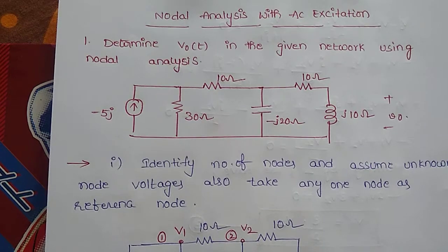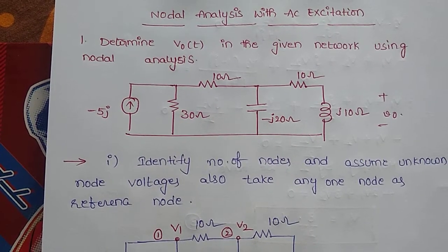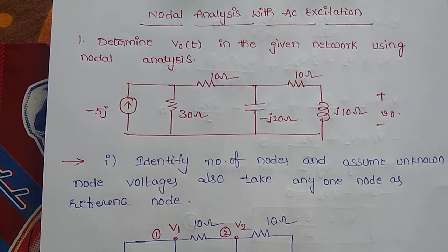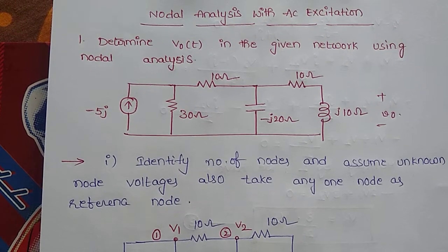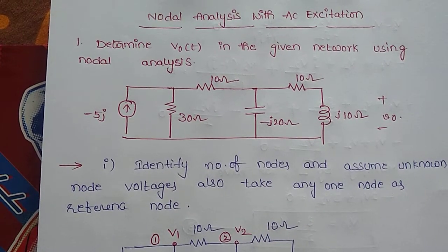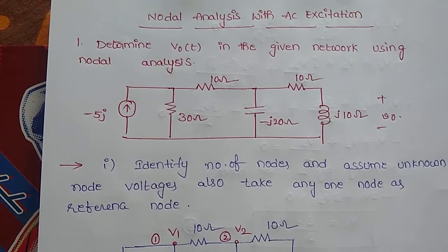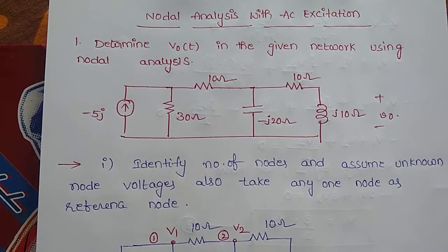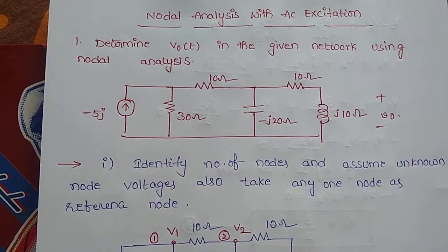Except that reference node, we are going to apply KCL at each and every node and write its KCL equation. Later on, after solving these KCL equations, we will get the unknown node voltages. That's why this method is also called the node voltage method or nodal analysis.